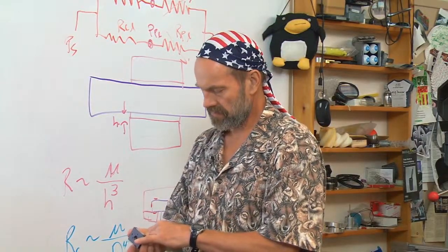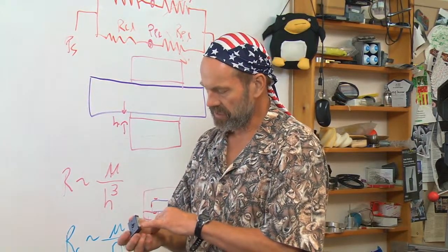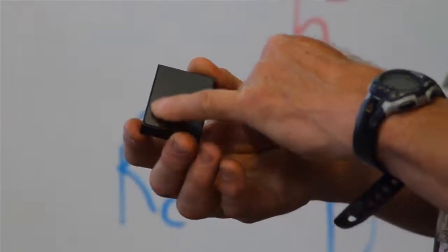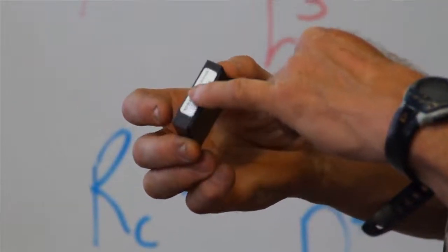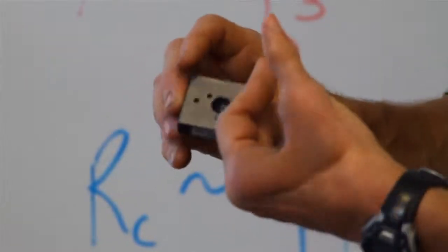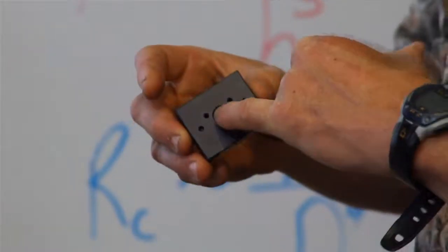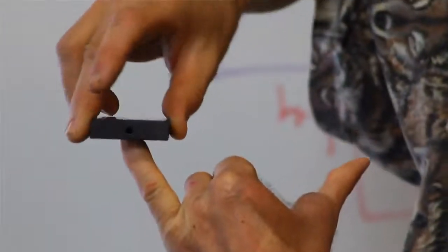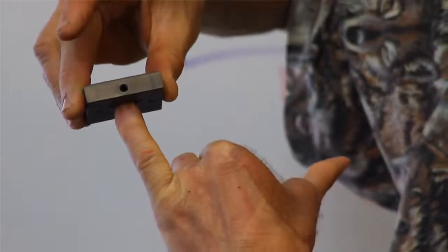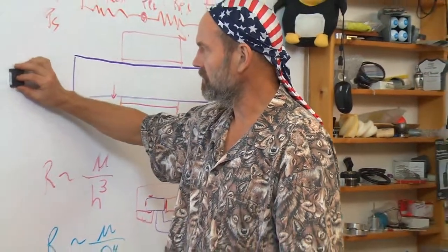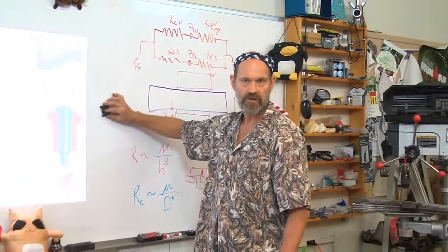And what New Way does, he takes porous graphite, bonds it into a metal housing, then, for example, a spherical element allows it to tilt self-aligned but very stiff rigidly in the axial direction. Put the air in, and then with air in, it'll float on a thin layer of air.